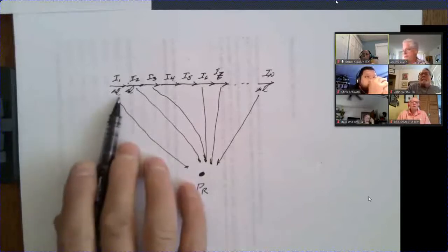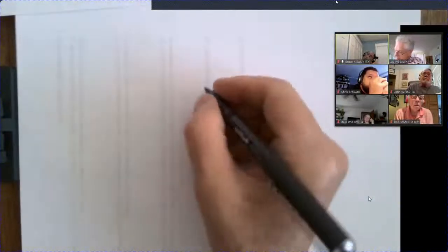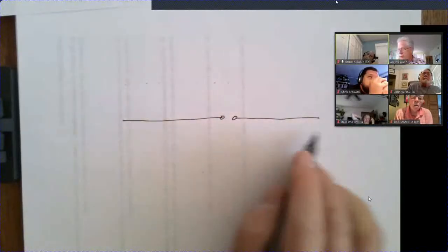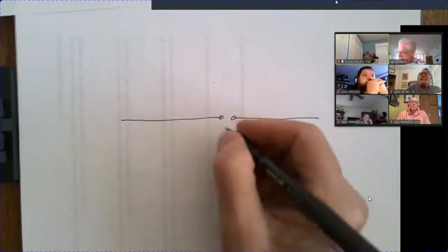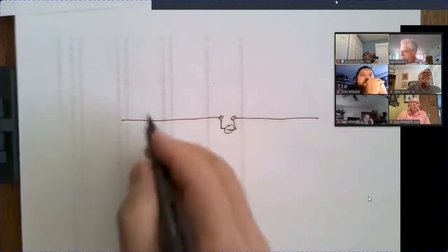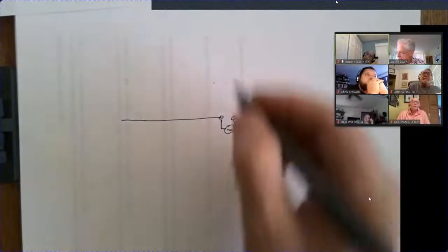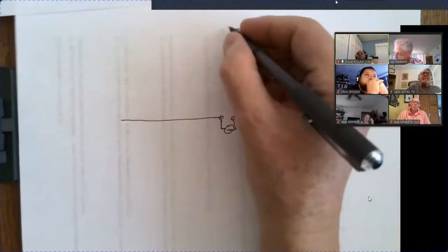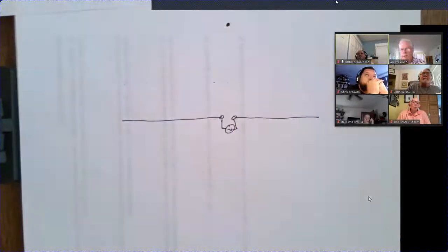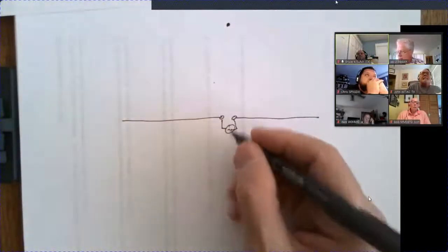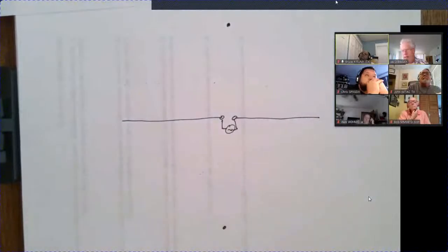So like, for example, it turns out that if we have a half-wave dipole, so it's got 2 quarter wavelength wires, and it's being fed by our little transmitter here in the middle, and it's going to be generating a pattern of power. Well, it turns out if you're straight off the ends, if I draw a line straight away from the center here, you get lots of power. If I'm saying the distance from this point here is proportional to how much power I'm getting. And then going the other way, we also get a lot of power.